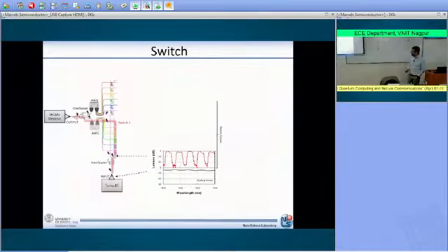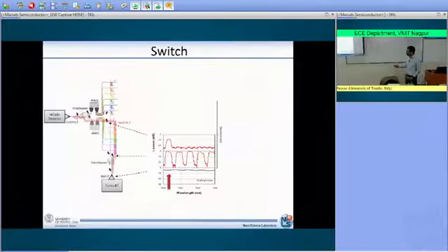And then you actuate the switch, and you measure whether the switch is able to switch the proper channel. What you see here is that after the switch, instead of having all those channels going through, you have only one channel that is switched off. In this way you are able to address exactly this wavelength color to this output.